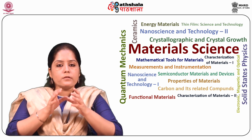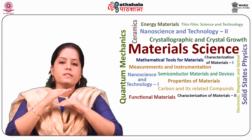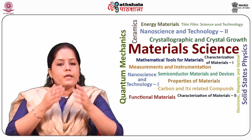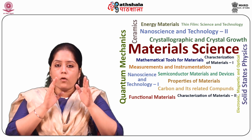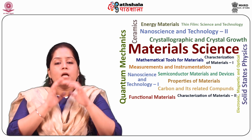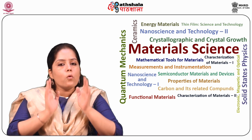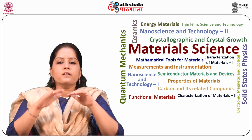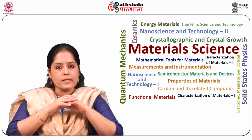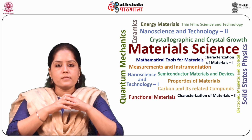It is important to note that the deposition of silicon dioxide, for example by CVD, is not called oxidation. Thus the term oxidation is used only for converting the existing layer of silicon to silicon dioxide. Thus, it is a modification process.